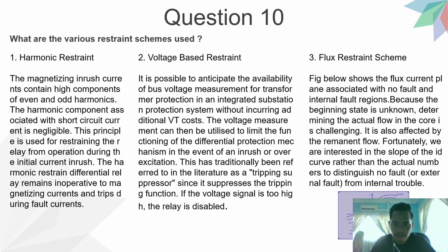Okay, next we go for question 10, which is what are the various restraint schemes used? Okay, there I have three, as you can see here. First is harmonic restraint, second is voltage based restraint, and last is a flux restraint scheme.